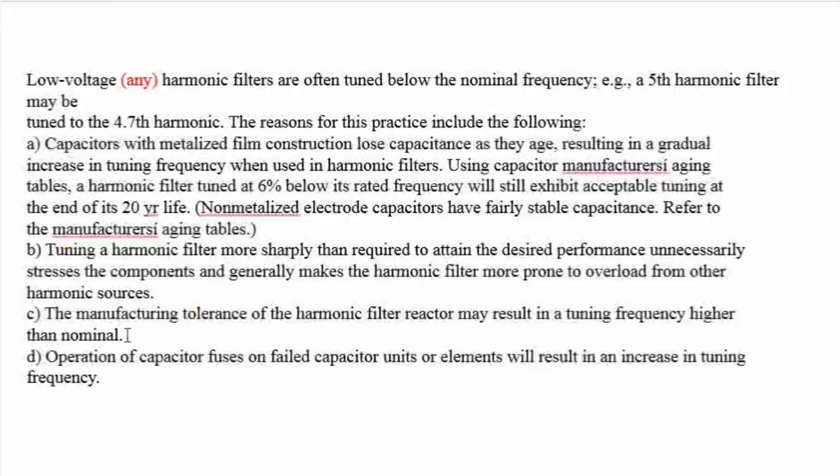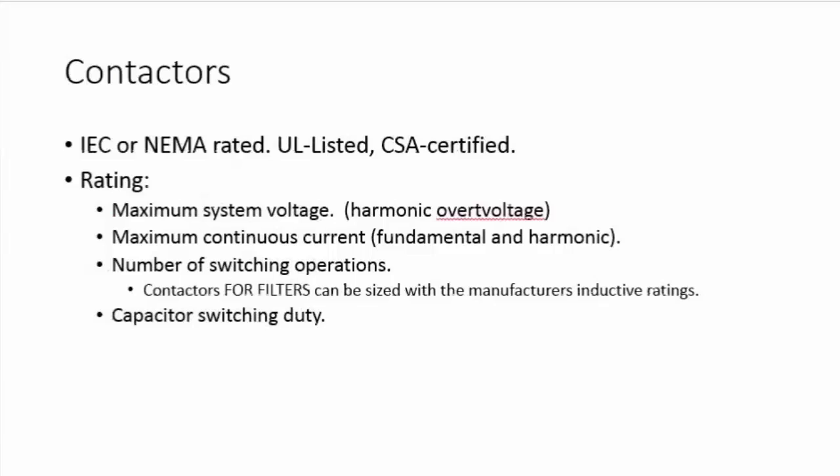Now, remember that the reactors and the capacitors have tolerance, so you have to account for it. And when a capacitor fails, it short circuits, and it may change the whole tuning of the filter.